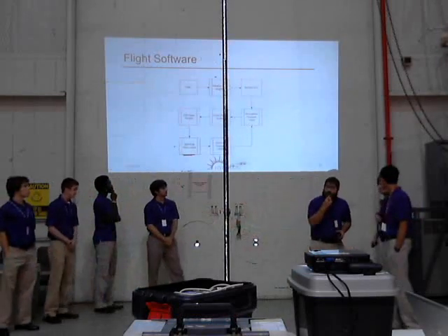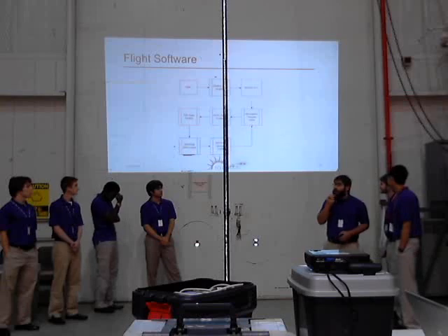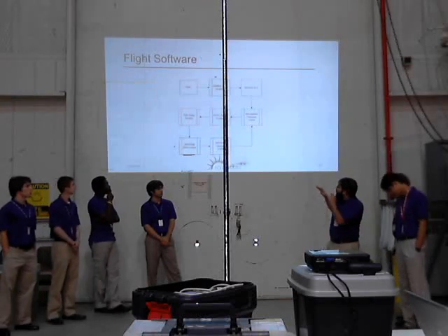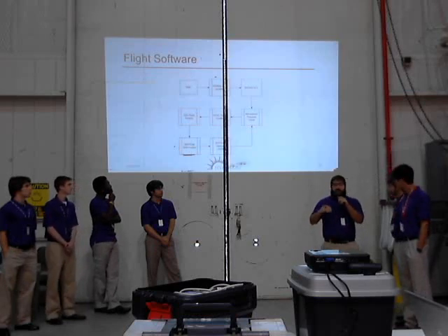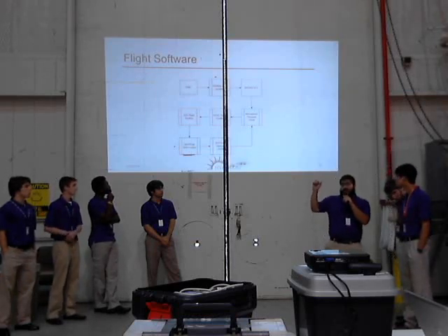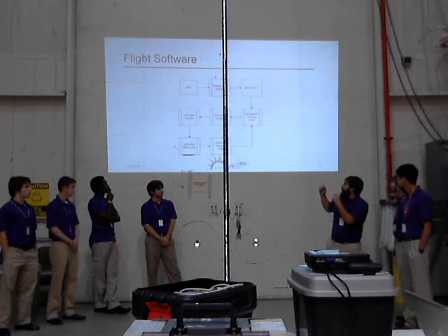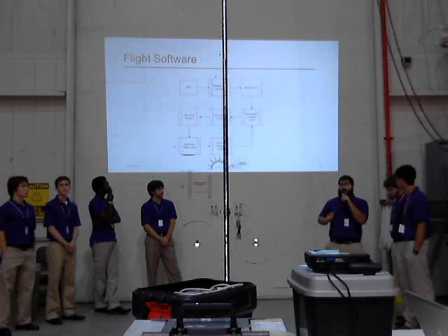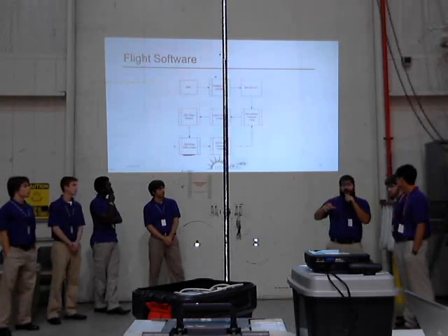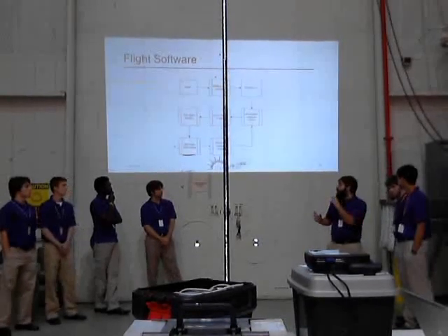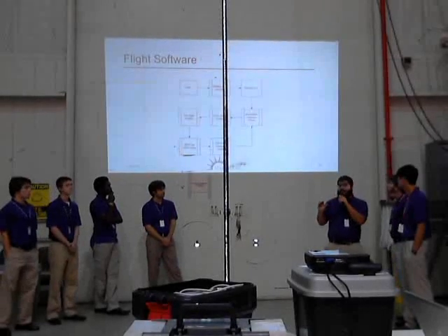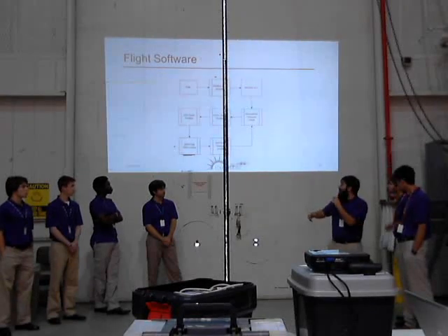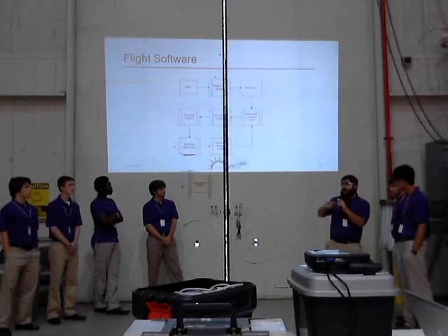The flight software runs in a modulated process, first checking to see if we are on the ground. The flight software does not actually work until we get up to about 2,000 feet. It begins by setting the DAC to 0, which resets the HVDC back down to 0, moves on and actually starts ramping the HVDC up, constantly checking to see if there was a spark. If a spark is detected, it takes a data point, taking all the environmental values, and then writes all of these values from the environment and the spark gap to an event in the EEPROM, and then it checks to see if the EEPROM is full and runs back to begin the loop again.